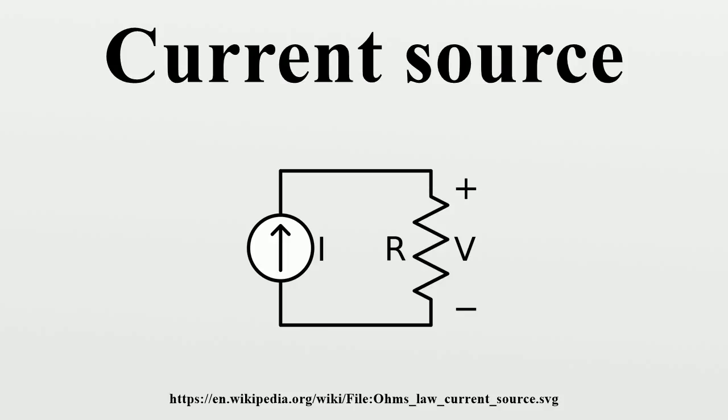Resistance R2 is now calculated as shown, since VD equals VBE equals 0.65 V. R1 is calculated as shown. This method is most effective for Zener diodes rated at 5.6 V or more. For breakdown diodes of less than 5.6 V, the compensating diode is usually not required because the breakdown mechanism is not as temperature dependent as it is in breakdown diodes above.